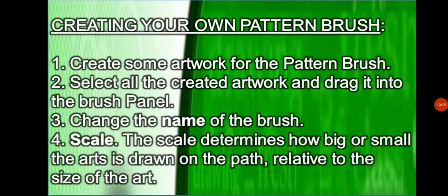Number 1 is to create some artwork for the pattern brush. Gradients and effects cannot be used when creating a pattern brush. Number 2, select all created artwork and drag it into the brush panel. When the new brush dialog opens, select new pattern brush from the options to bring up the pattern brush options. 3, change the name of the brush.